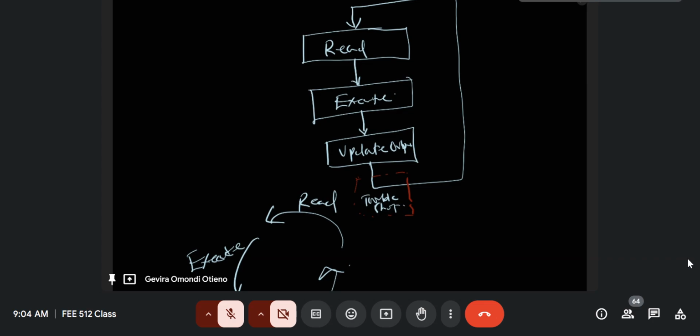So at this point for our study, I want us to restrict ourselves to the 3-step operation of the PLC, where you read instructions, you execute the program, and then you update the output status. I'm emphasizing this because I know some people will read the book by Petruzella and they'll see a 4th stage or a 4th step in the scan cycle that has been introduced, and it's called diagnostics and communication. Now, like I've told you, you don't have to diagnose your processes during scan cycle when there is no fault. So we'll stick to the 3-stage scan cycle, where you have to read, execute, and update.